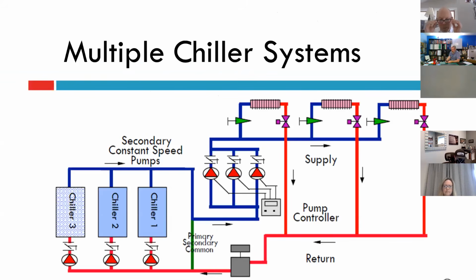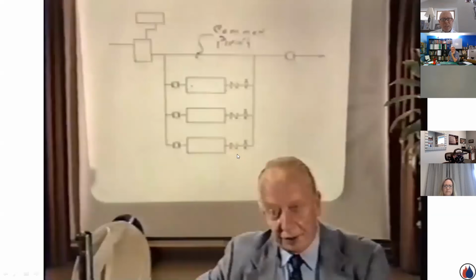Again, here's a quick example, very common, multiple chiller system. You see this a lot in perhaps a college campus distribution, feeding classrooms, offices, dormitories, certainly in hospitals, college institutions, etc. Again, fortunate enough, he actually talked about this that far back, showing primary, secondary. Here's my common pipe. I have a distribution, and here are my 3 chiller barrels. So he was referencing that primary, secondary had a place with large chilled water applications.